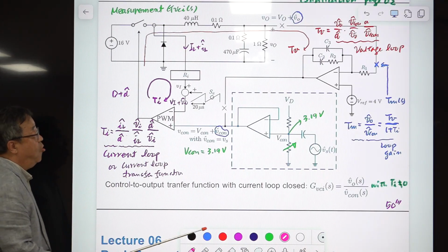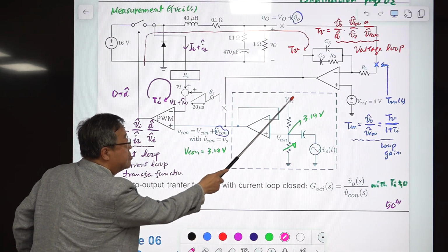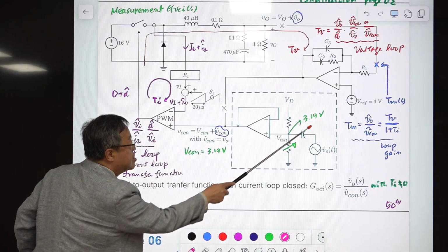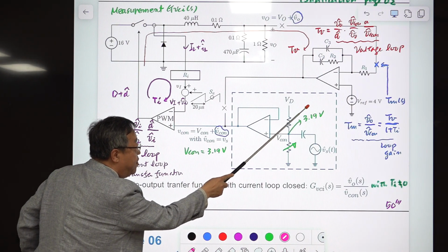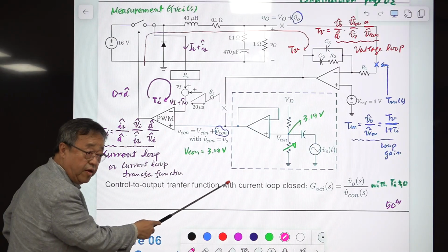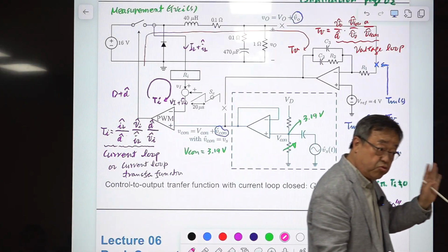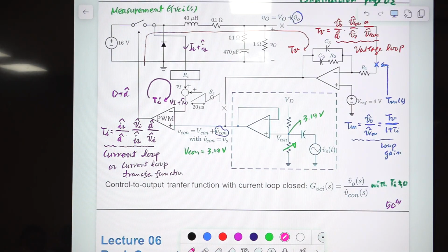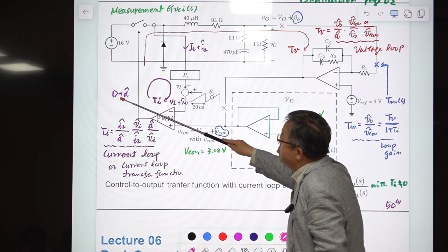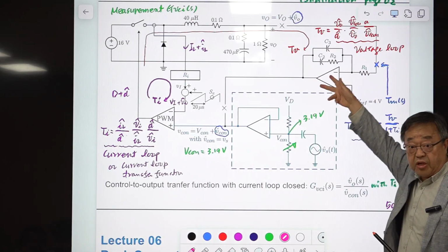All right. Then the way of doing this is, this is 0 initially. Then you add some voltage here, maybe 5 volt. This is R, and you adjust this and make this 3.19, and this is the unit gain buffer. Then this DC voltage is this one. Last time I got confused. I was saying something stupid. 1/4, that is not true. And you put this number here, then D becomes 1/4, and the output becomes 4 volt, because of the previous analysis.